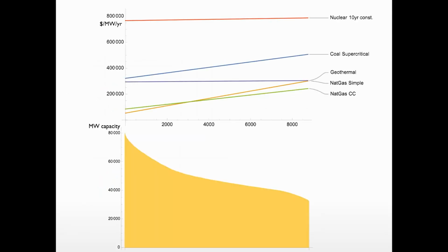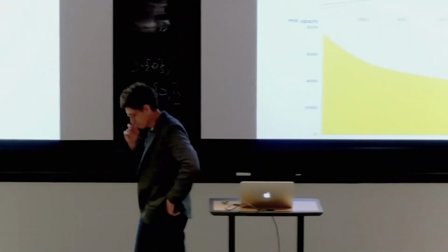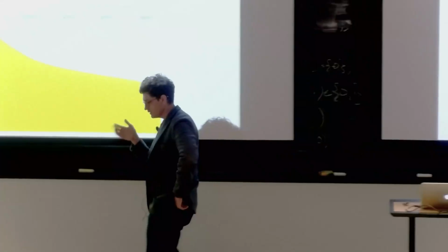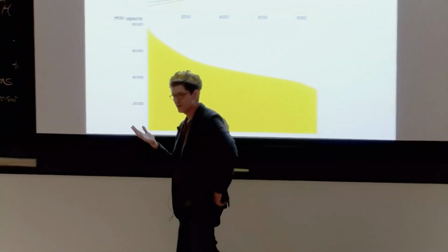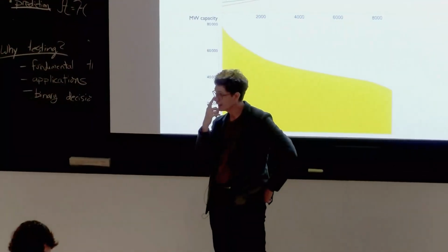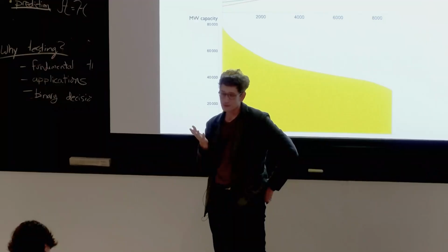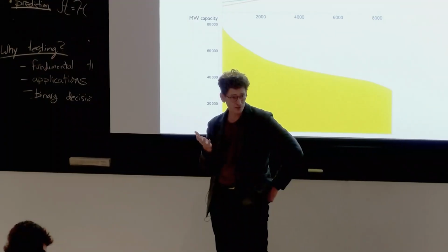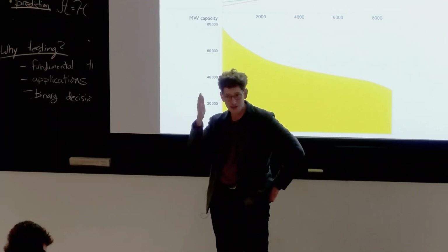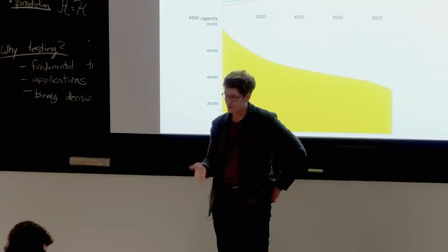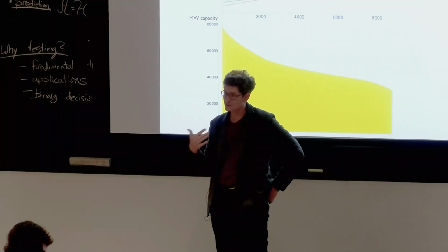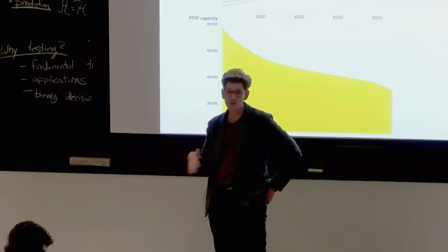All right, so now you know how to dispatch different amounts of material, or different numbers of plants. Since we're talking about bidding, let me just mention one thing. Sometimes prices for electricity will go negative because there's a bunch of generators on the grid, and demand drops, and it's a market signal to get your generators off the grid now, or we're charging you.